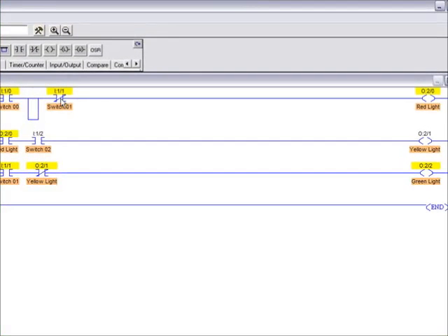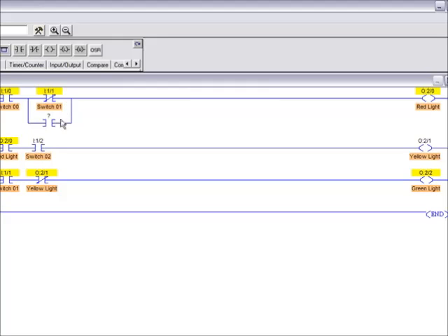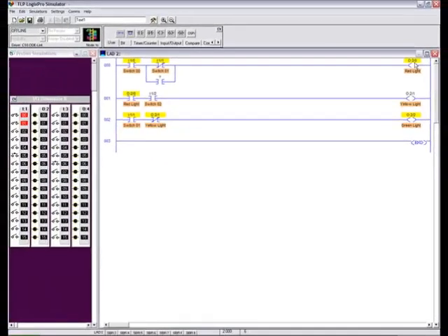So what I need to do is click on switch 1 and drag it into, or in between, the two vertical sides of the branch itself, like so. And if I look on page 8, I also need to add a normally open contact with the address O:2/0. Now there's two ways I can add this address.